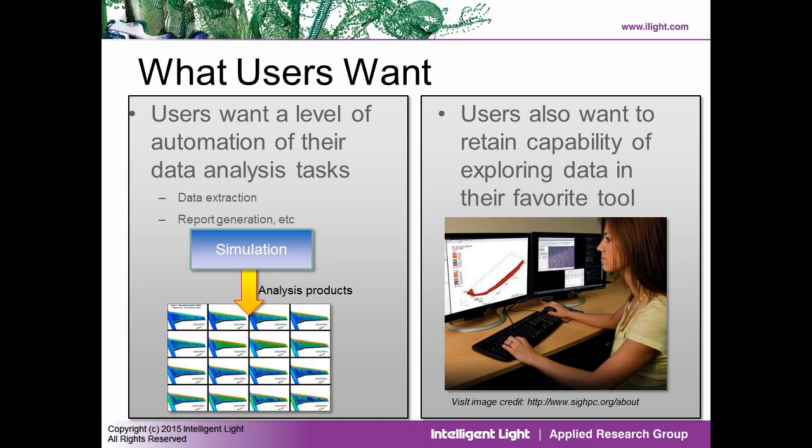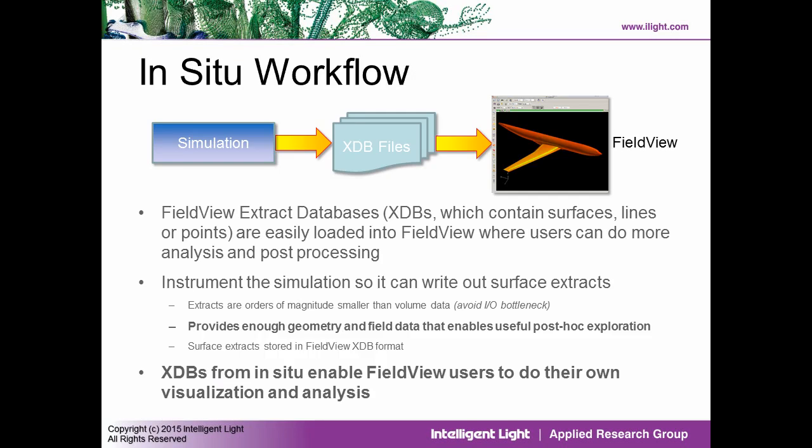On the far end, what we find is users still want to be able to do the traditional post-analysis with their favorite visualization tool. So a way to accommodate this is by using data extracts. We've created this in situ workflow whereby we instrument the simulation with VisIt and LiveSim, and then that is able to create XDB files, which can then be processed by FieldView. XDBs are the FieldView extract databases, and of course FieldView natively reads those and consumes them quite efficiently.